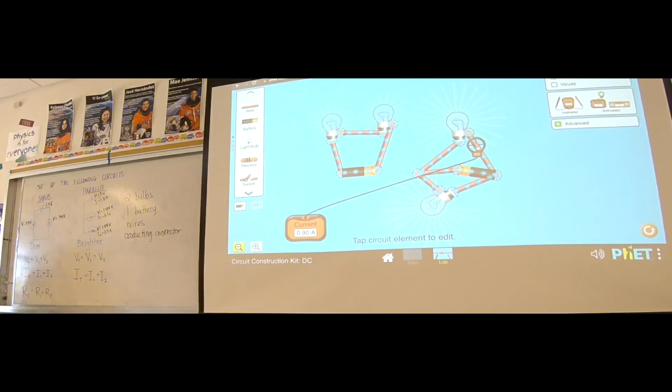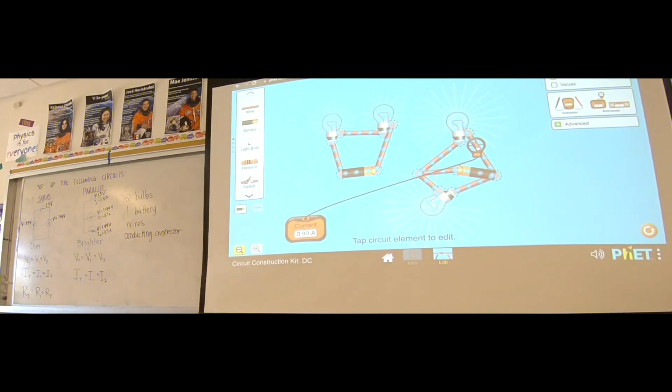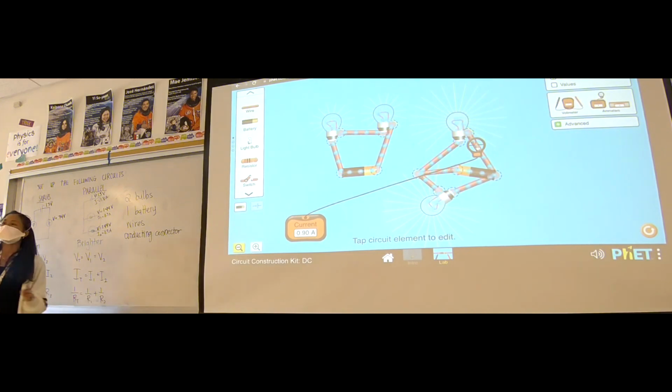If I add two resistors in series, it's going to create more resistance. The odd thing is that if I had resistors in parallel, you're not adding the resistance of each one, but you're adding up the inverse of each resistance and then taking the inverse of that total. Weird. But we're going to do some calculation with it. What actually ends up happening is that by adding resistors in parallel, you actually decrease the total resistance so that it's even smaller than each of the individual resistors combined.